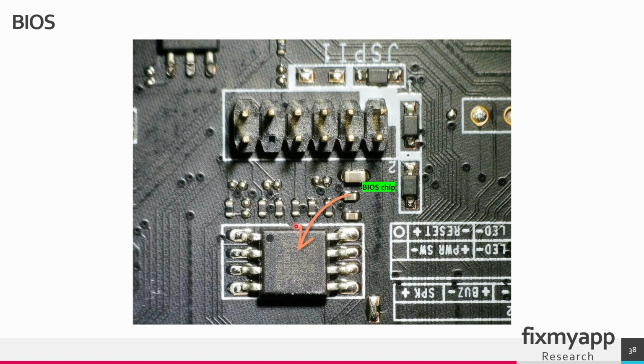I verified the power supply's output using a multimeter to ensure it was providing a stable voltage. A failing PSU can cause erratic behavior or complete failure to boot. From there, I tested each RAM stick individually in different slots to rule out any memory issues. I also double-checked the CPU for signs of bent pins or improper seating, as these are common sources of boot problems. If no issues were found during these checks, the next step would be flashing this BIOS.